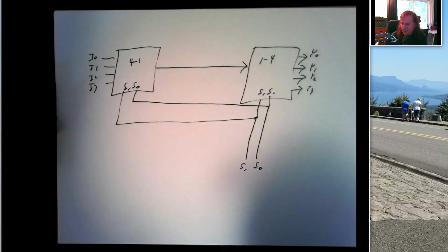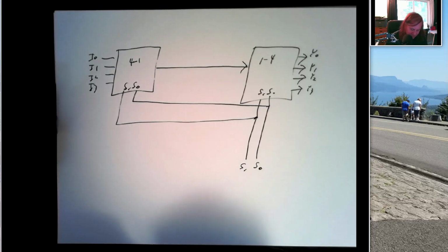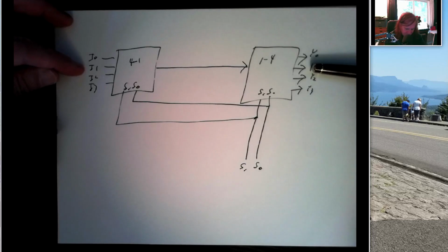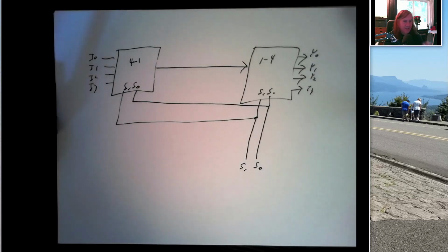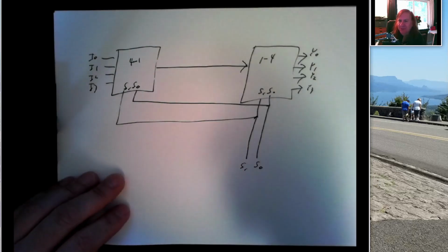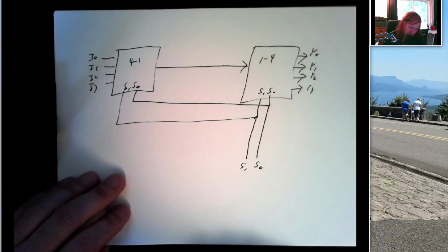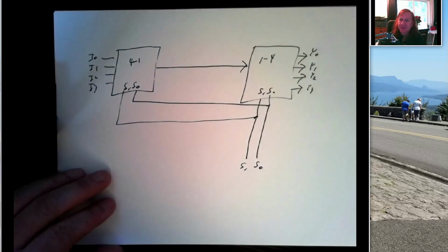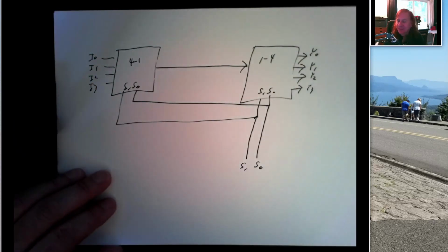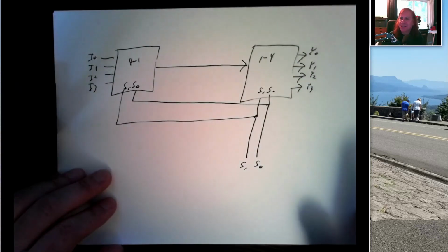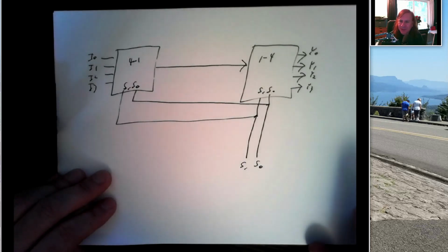But I do it in what we call time multiplexing. Over time, I change this pair of inputs so that first I send I0, and then I1, and then I2, and then I3. And this is also something similar to what we find inside a CPU, where we might generate the result from an adder and want to send that to different parts of the units. Well, we could use a demux for that. So these are also useful blocks, and this is one way where we can put a demux and a mux together and get some good behavior coming out.